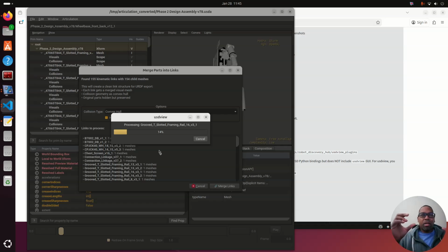And instead of having this complicated thing with 100 or so parts, now I've simplified it down to just a few STL file meshes that represent the robot. You still get the mass, you still get all the physics that you need. I'm just compressing that down. The original parts still exist. There's nothing changed or removed about them, but now they're just part of a bigger picture. It's much better for performance, especially if you're going to use that in Gazebo or editors that require a massive GPU and cannot ray trace all of these points. We simplify all that. We bring it down into something much more simple.